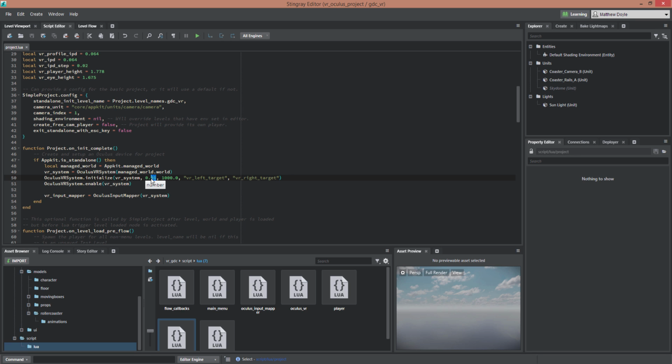Now, keep in mind that these values will affect your frame rate with the headset, obviously. So you want to be very careful to make sure that you don't set your far clipping plane too far, and you don't set your near clipping plane to be too small, too granular. Now, if you have a game where you have lots of indoor tunnel-y type stuff, you can obviously set your clipping plane pretty low, and that's going to help your performance. In the case of our roller coaster demo, I went ahead and stayed with 1,000 meters, which is the default setting here. But in the case of the near clipping plane, I'm going to go ahead and change this to 0.1.